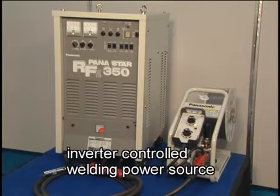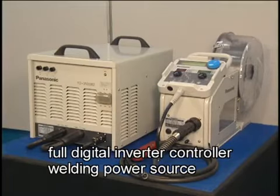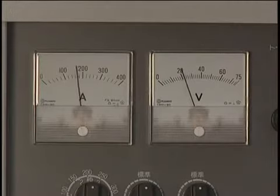The welding machine for the MAG welding process is basically the same as the welding machine used for the CO2 welding process. As for the basic parameters of the MAG welding process, the welding amperage, arc voltage, travel speed, and the torch control affect the weld bead in the same way as the CO2 welding process. We will explain the MAG welding process mainly by arc phenomenon.